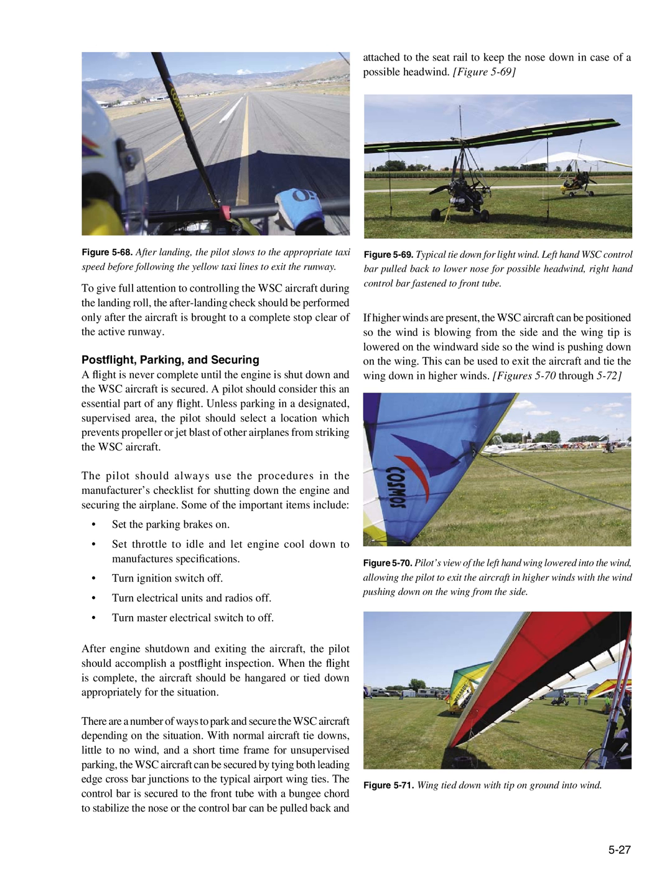Post-flight, parking, and securing. A flight is never complete until the engine is shut down and the WSC aircraft is secured. A pilot should consider this an essential part of any flight. Unless parking in a designated, supervised area, the pilot should select a location which prevents propeller or jet blast of other airplanes from striking the WSC aircraft. The pilot should always use the procedures in the manufacturer's checklist for shutting down the engine and securing the airplane.